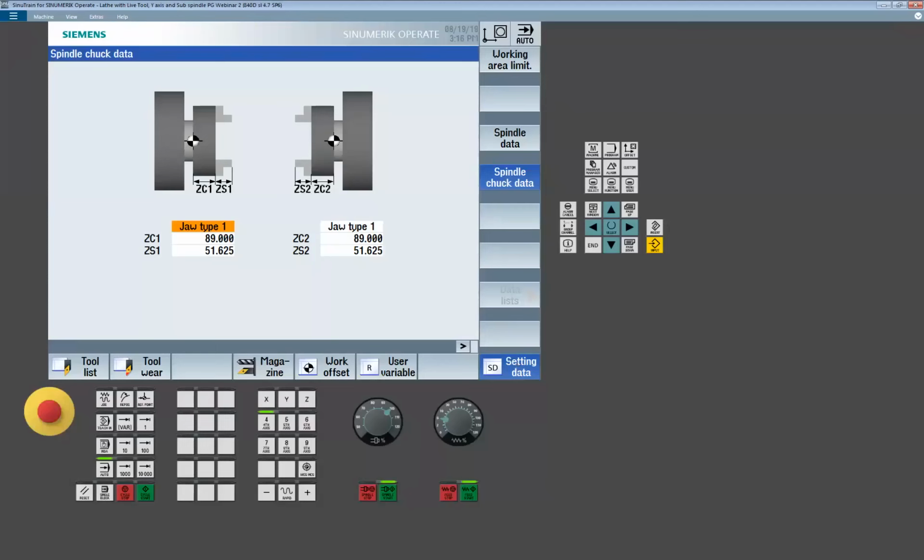Can you use the $P_TOOL L index 1 instead of using D0, as you might have a D2 effective for the retract, as we do on the mills? Sure, we could. So that is just accessing the system variable for the tool length. We could do that for the SUPA.